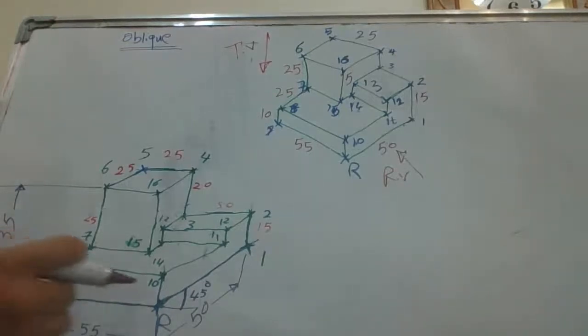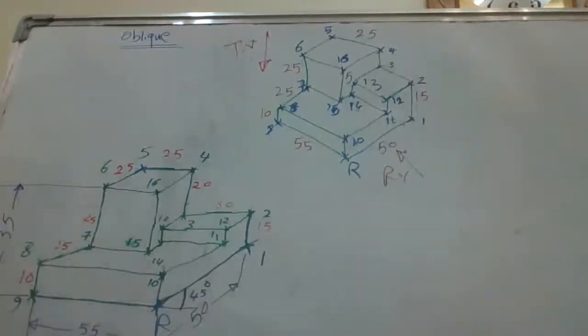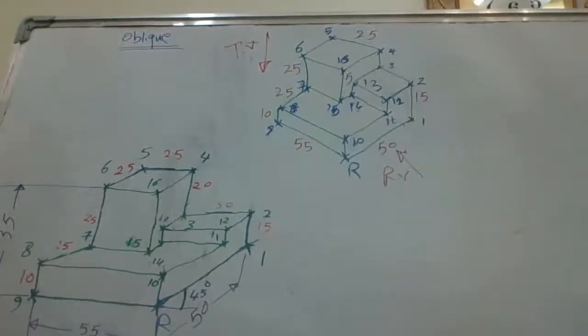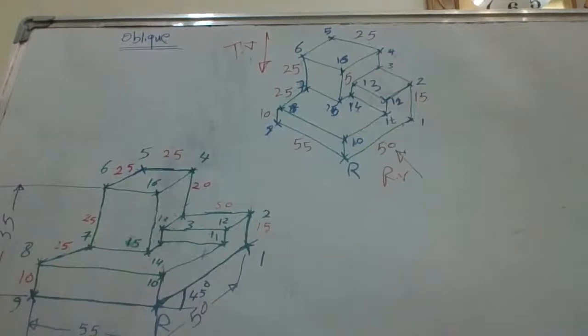Now we can choose the suitable lengths which we can put here, so we can guess the others. We are not allowed to draw all the dimensions. We just draw the suitable ones, the minimum number of dimensions that can determine all the other dimensions.